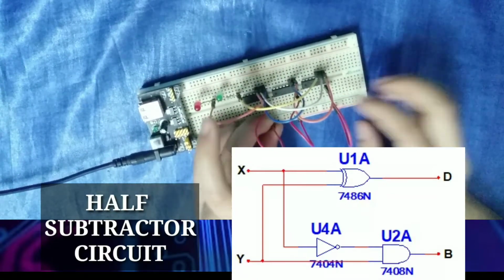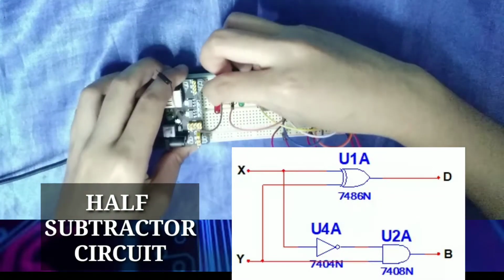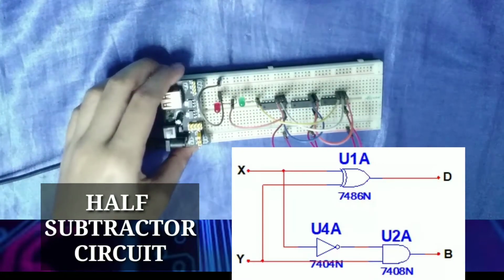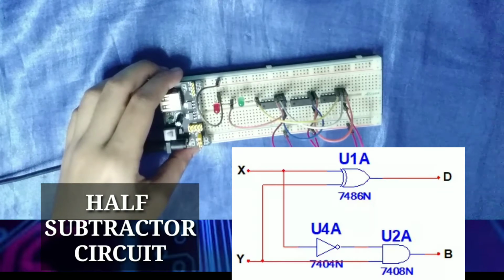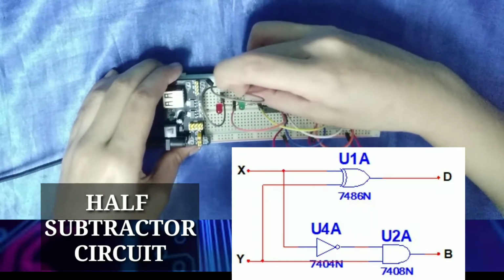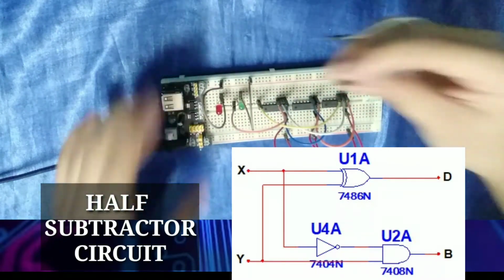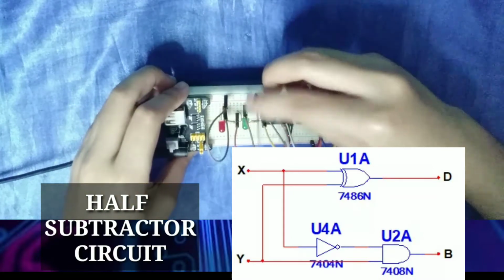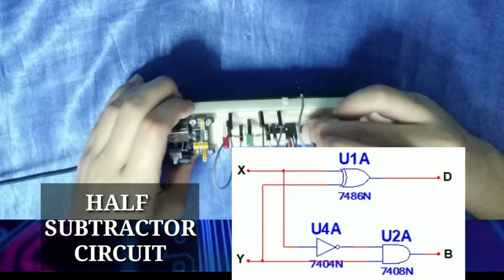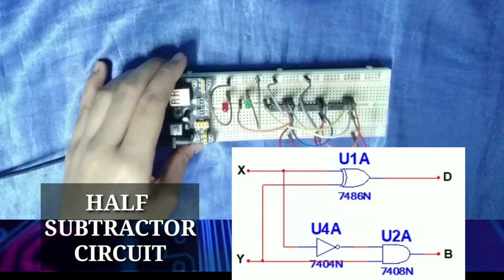And do not forget, this is really important, to ground all of our components. First one is our output for the borrow, which is the red LED. Our output for the difference, which is our green LED here. Okay, let's not forget to ground all of this. And of course, the grounding for the 7th pin of each of the integrated circuits here on our end. So don't forget, because it's really important to ground all of our components.